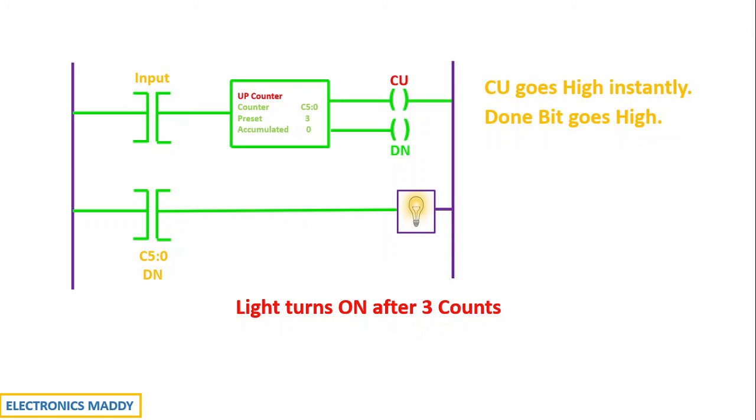Having seen this, one of the most important concepts is the timing diagram. This is important because at times you may be confused with the concepts, since there will be up counter, down counter, on delay timer, off delay timer. These are all different concepts, and if you know the timing diagram, you can arrive at the concept on your own. I'll tell you how. Let us look at the timing diagram with respect to the bits.